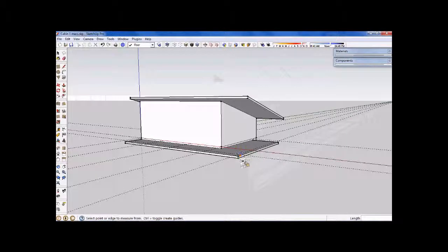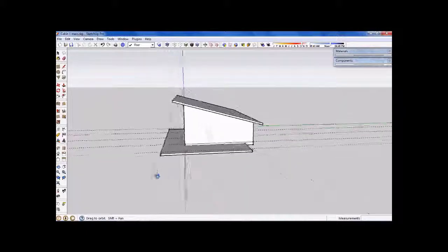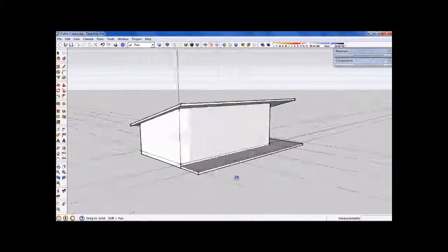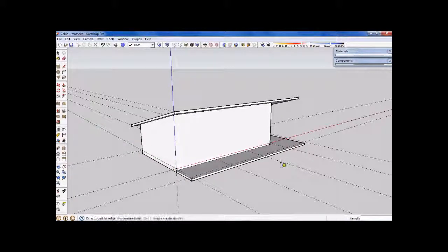So we've constructed our floor slab for the veranda and carport area, which is 150 millimetres below our datum. So this is where I'll go back now to the roof layer. Set the roof layer as the next active one. That's a bit of a milestone there, so we might actually do a save right here to make sure we keep all of that. And I'll pause the video for a second, and we'll do the roof as the next step.